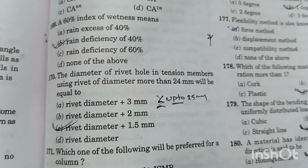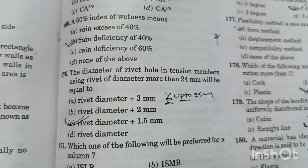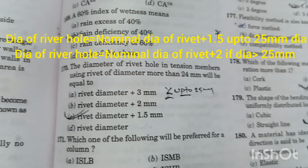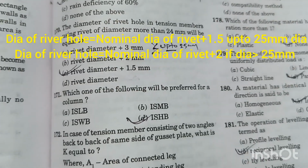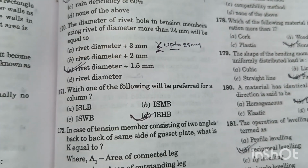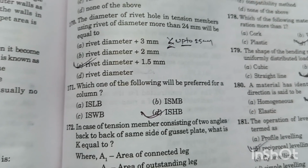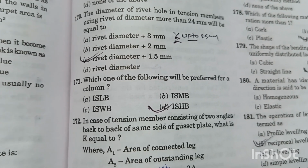Question number 170. The diameter of rivet hole in tension member using rivet of diameter more than 24 mm will be equal to rivet diameter plus 1.5 mm. Option C is the right answer. Question number 171. Which one of the following will be preferred for a column? ISHB, Indian Standard Heavy Beam, will be preferred for a column. Option D is the right answer.